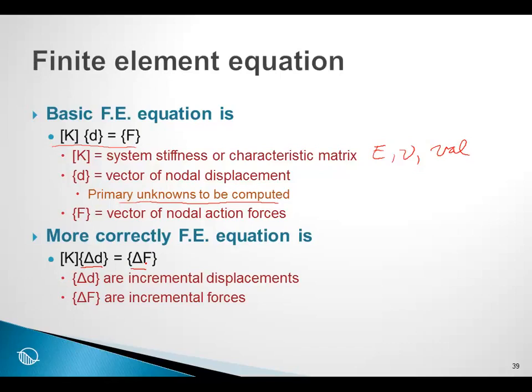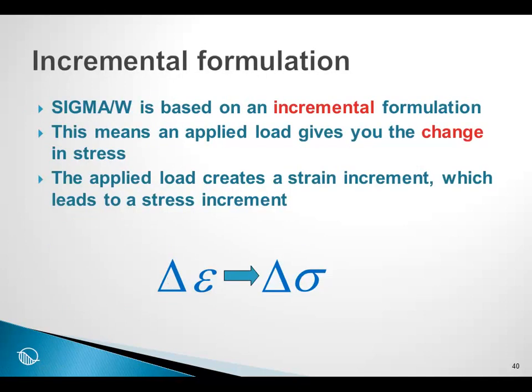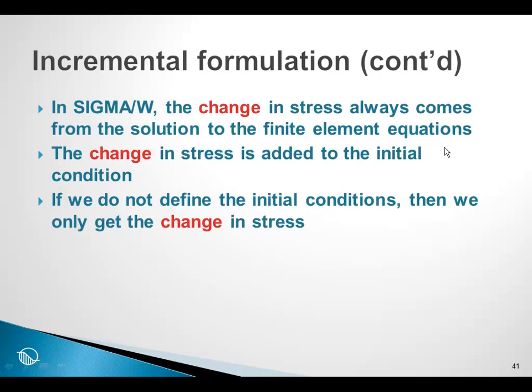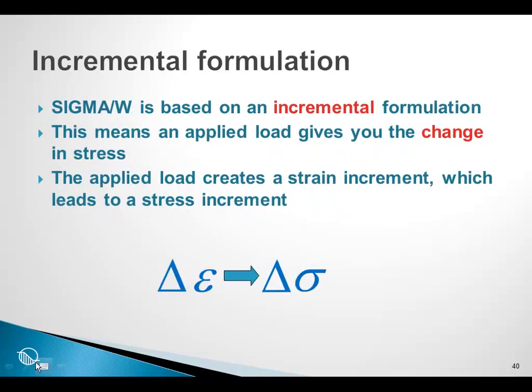We have just shown that we applied a surface pressure, that we got the change in stress in the ground. We didn't get the actual stress in the ground. And that is because SIGMA/W is based on an incremental formulation. This means that an applied load gives the change in stress as we have just talked about.